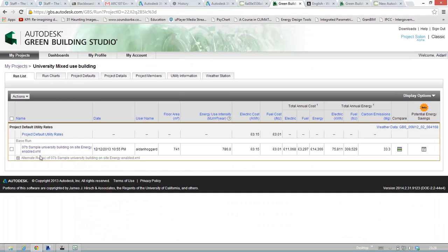If you want to then bring the model into the site in Revit, it would appear you will have to go through the GBXML export route and import that into Green Building Studio. If you want to try other energy analysis packages, you could of course at that point import that GBXML file into Ecotect or into another package, but I'm not covering that in this tutorial. Okay, so we'll end it there.